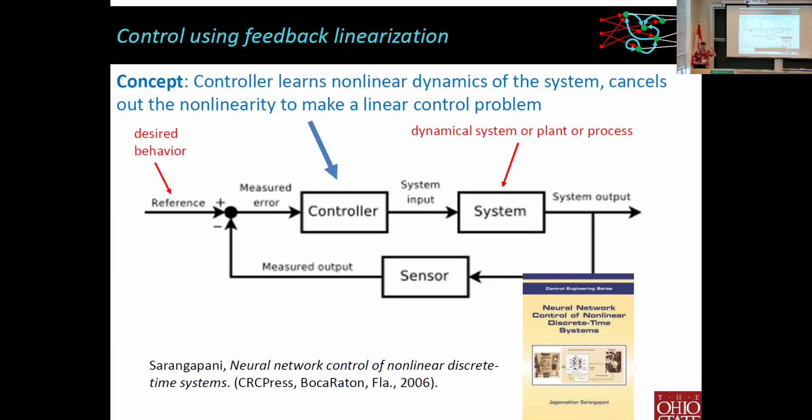What I should say is that in almost any experiment nowadays, we don't build analog circuits anymore for trying to do control. I used to do that a long time ago, but now any type of modern system is going to have an analog to digital converter that's going to take that underlying analog signal, turn it into a digital number, and then I'm going to have some kind of control algorithm. I then send that out through a digital to analog controller to then perturb the system. And so it's inherently a discrete system because I'm sampling at some interval. And so I really should be using concepts from discrete time control.